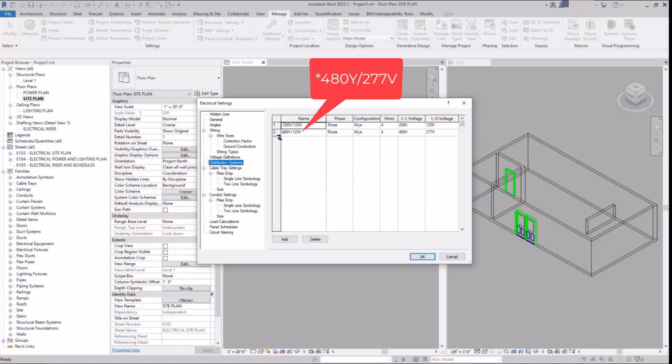And then distribution systems. Here in this project, we're going to be using 208Y and 480Y. There's obviously 120/240, which is single phase, which we've talked about. And then 240 delta, which can also be a high leg. So 240/120 is what you call that high leg. All right. Questions on that one? No questions.